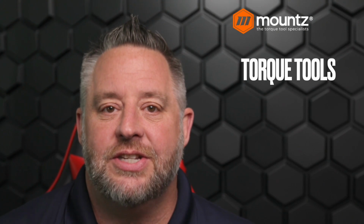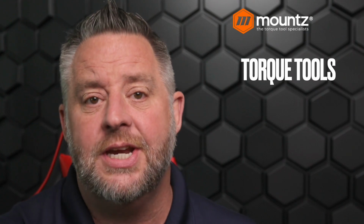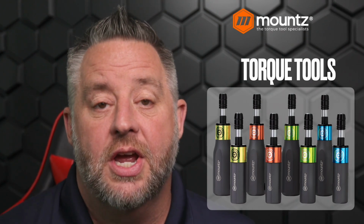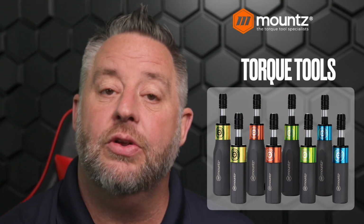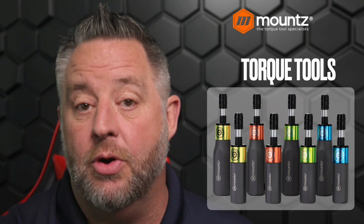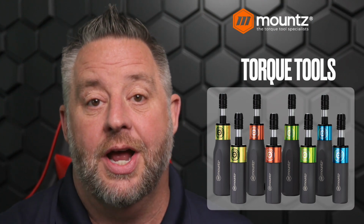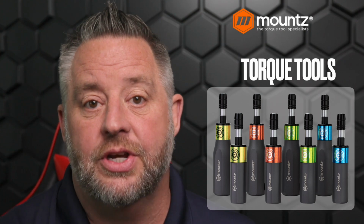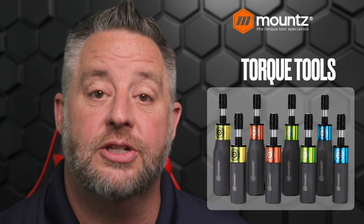And so this is going to lead us into the different types of torque tools that you would see in the assembly process. The first is going to be torque screwdrivers. Now, torque screwdrivers operate just the same as a standard screwdriver. The only difference is that once torque is achieved, that screwdriver will simply slip or cam over, and the torque value has been reached. There are a few different styles of torque screwdrivers that use different mechanisms to relay that torque has been achieved.